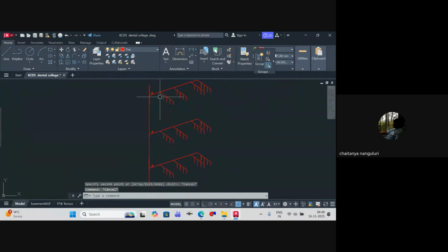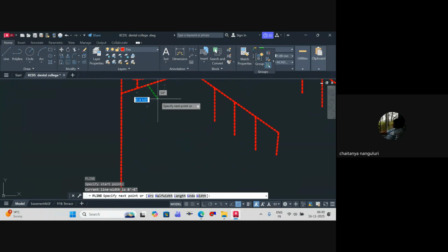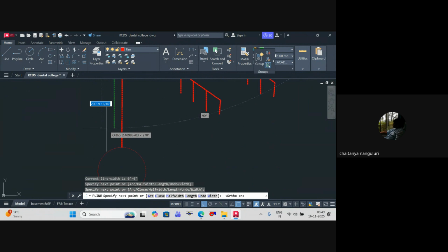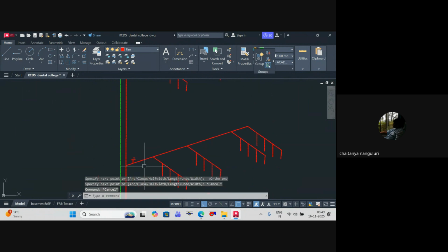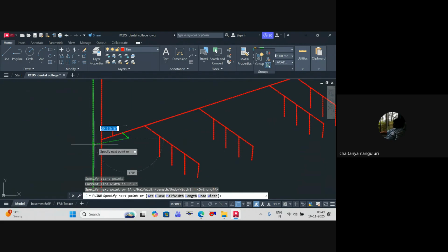So now coming to the drain point. You can either have a drain at this location. I'll change it to another color, let's say. Yeah, you can have a drain something like this. So from here, you will take one more header, which is your drain portion. You'll have an isolator valve, obviously, which will be connected to this again.